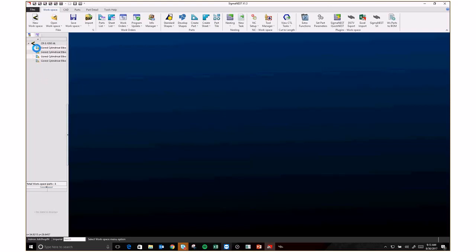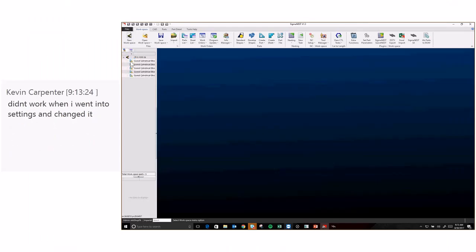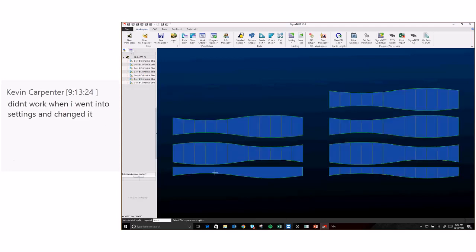And again, right here, you see the part, and it's got an exclamation point, a caution sign. Hey, something else needs to be done. So we're going to address that when those parts come in. So as you can see, those unfolded parts with the bend lines as no-cut parts are being brought in from Develop into Sigmatek. So it's easy now.